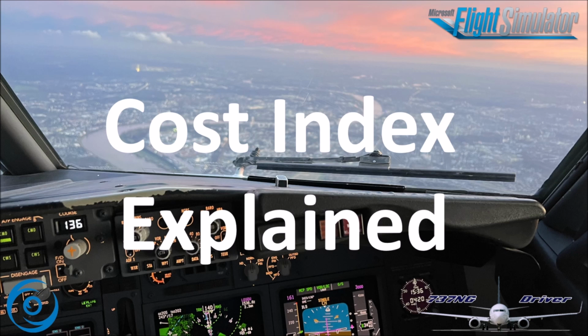You do have to note here that when flying at a cost index of 0, the climb is in general calculated for minimum fuel, the cruise for maximum range, and the descent for the maximum lift to drag ratio. When entering the maximum cost index, normally on all three phases of flight, the FMC is just going to go to VMO or MMO, so the maximum airspeeds possible.